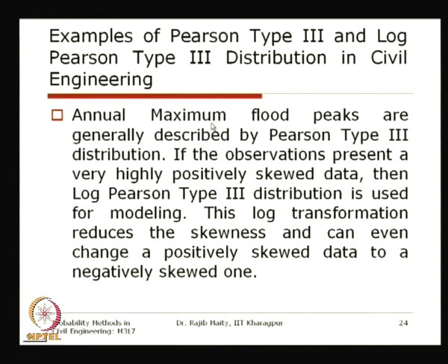In a year, from the data that we have, we pick up the maximum values, and when we model only those peaks, it is observed that the Pearson type 3 distribution is very important, particularly for frequency analysis, that is, the return period, which is very important for example to design a reservoir or dam.